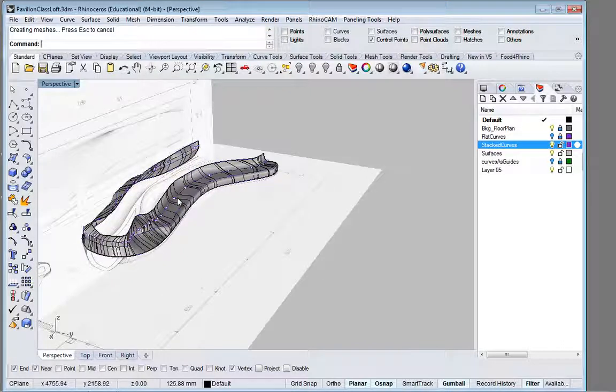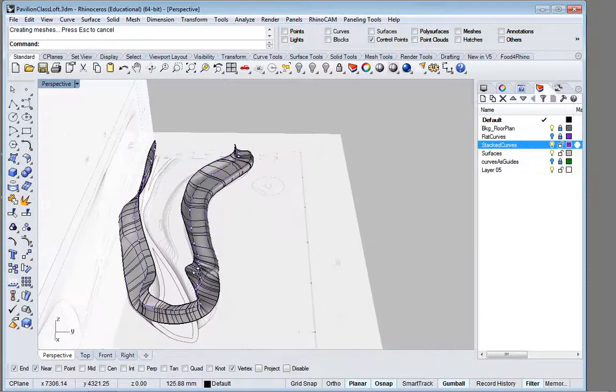You can choose to do it whichever way, but I think this lofting and then going back and editing the curves is the important one and the easiest one to do. And remember that record history is your friend. None of this becomes possible unless you use record history. You just have to keep relofting. So that's important. Then the next piece.